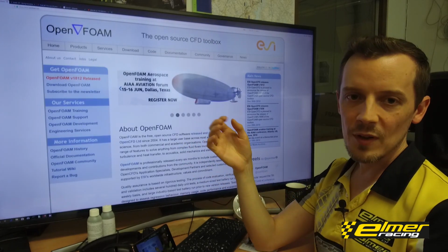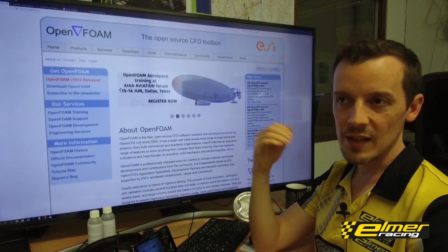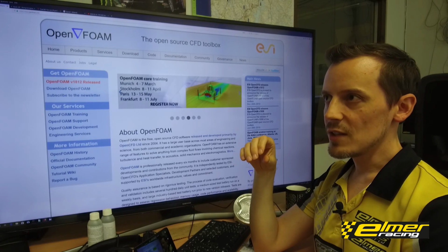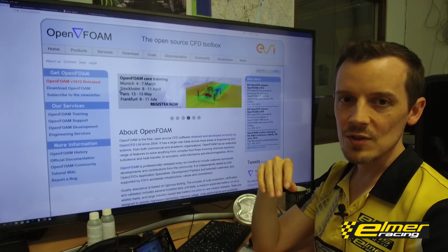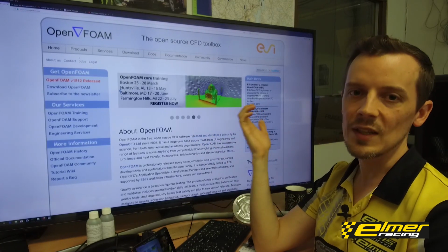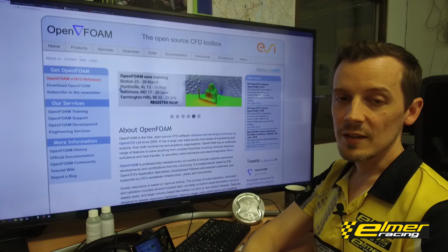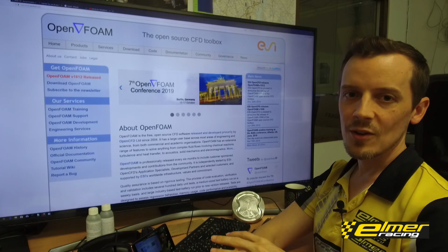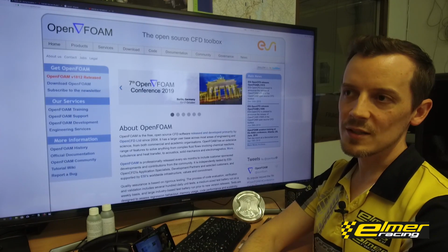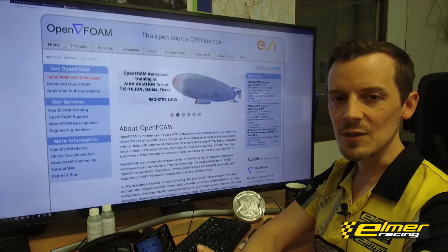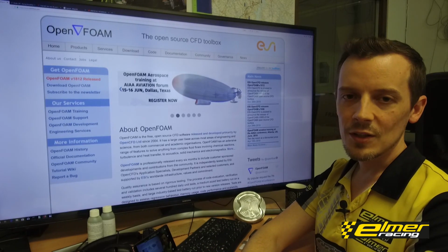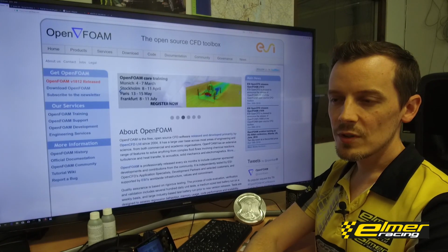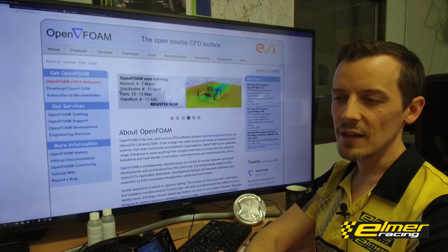You can end up with a car very easily that is 20 kilos heavier. That's even with a good design. If you have a car where the chassis is designed poorly, or by conventional means, you can easily end up with a chassis that weighs 50 kilos more. And as we went through in episode 1, if the downforce levels are high, then the weight of the car starts getting very important also. If you have a car that is 20 or 50 kilos heavier than what it needs to be, that is going to be a huge detriment to your performance. So it is important to look at all these kinds of things.